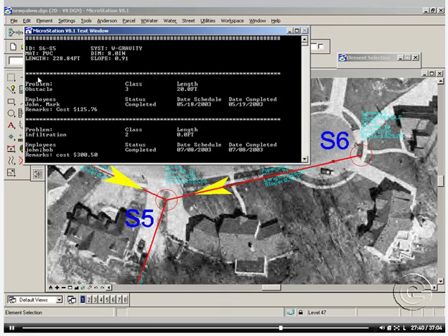And we could go back here and see the ID of the pipe, the material, PVC, the length of the pipe that we selected. It will show the system, the dimension, the slope of the pipe, and we can see all the problems that we have on that pipe. There was a problem here that was just an obstacle in class of 3 for 20 feet on that pipe, and we had assigned for that problem John Mark. It cost about 125. It was scheduled May 18, completed May 19.